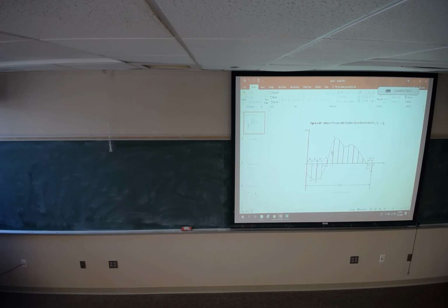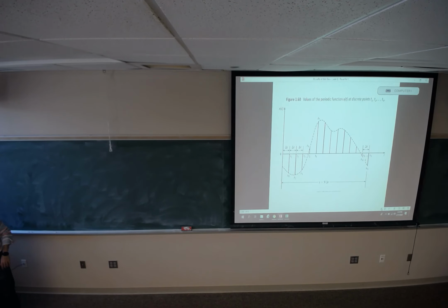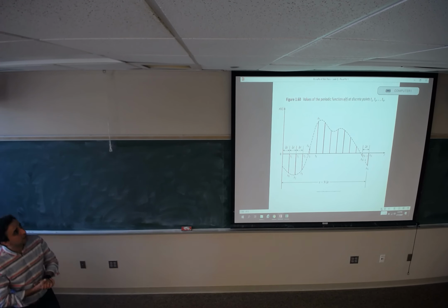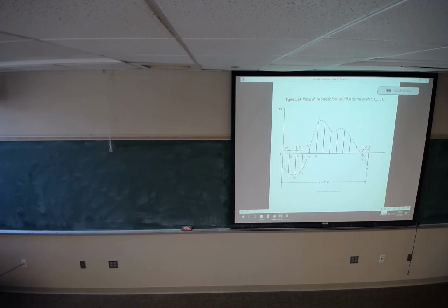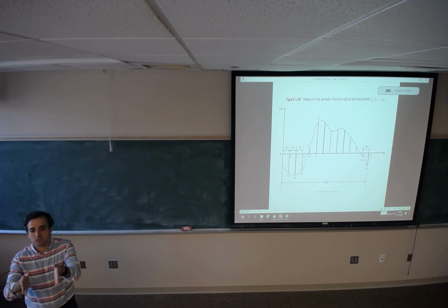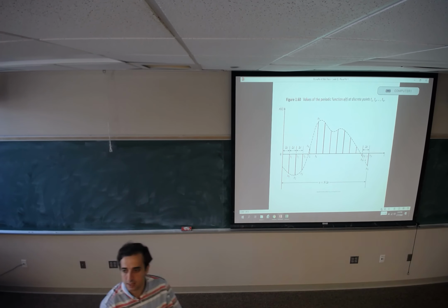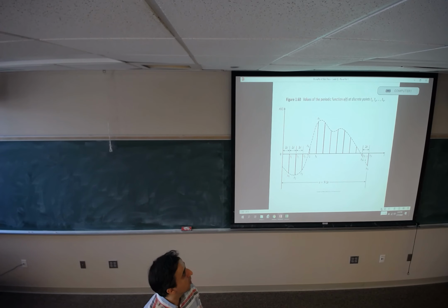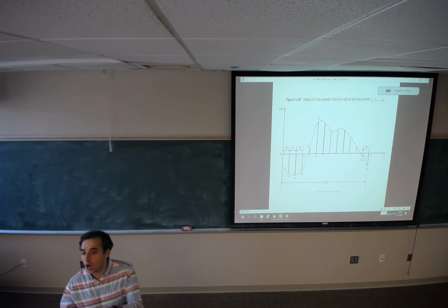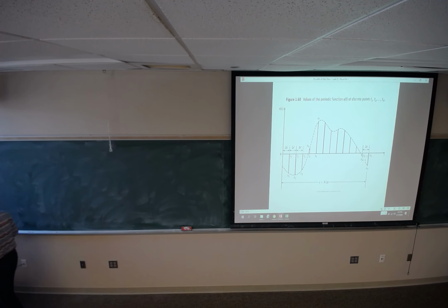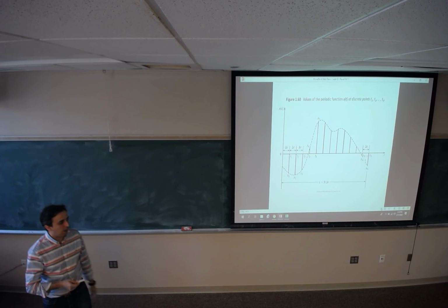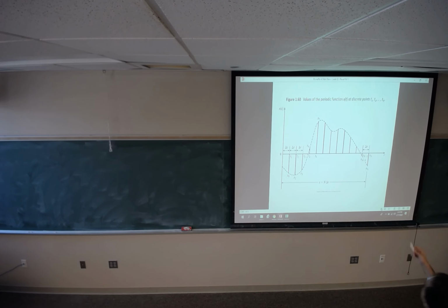All right. Let me finish the signal processing. So we learned how, when we are given a periodic function, a motion which is going to repeat itself regularly, we can convert the periodic function or motion to harmonic motion by applying the Fourier series. So that can be applied for continuous functions, but what if we have discrete points?